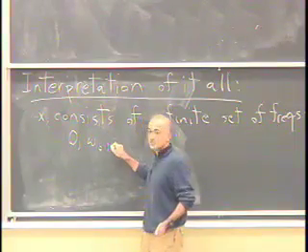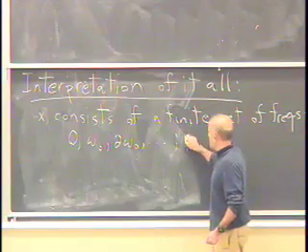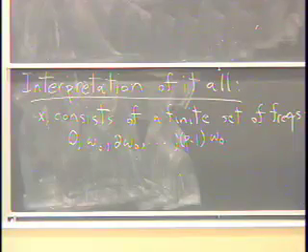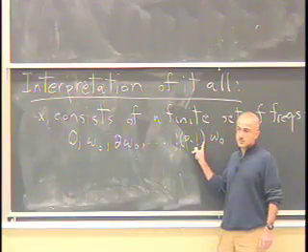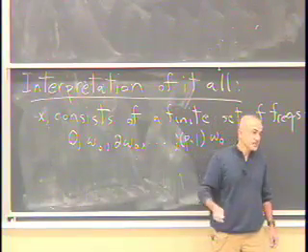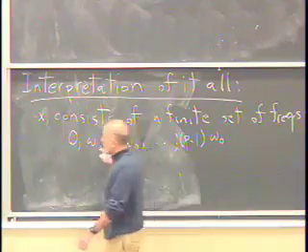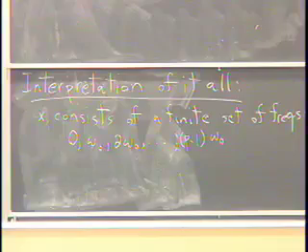Omega naught. 2 omega naught. P minus 1 omega naught. In other words, a signal that is periodic with period P cannot contain any frequency other than this set. Now, some of these frequencies may be absent from our signal. That's possible. How do you know if a particular frequency, let's say omega naught, doesn't contribute to our signal? The corresponding coefficient will be 0.